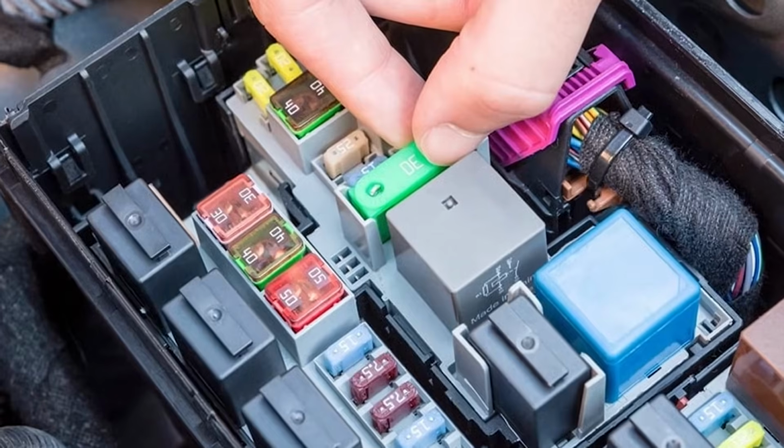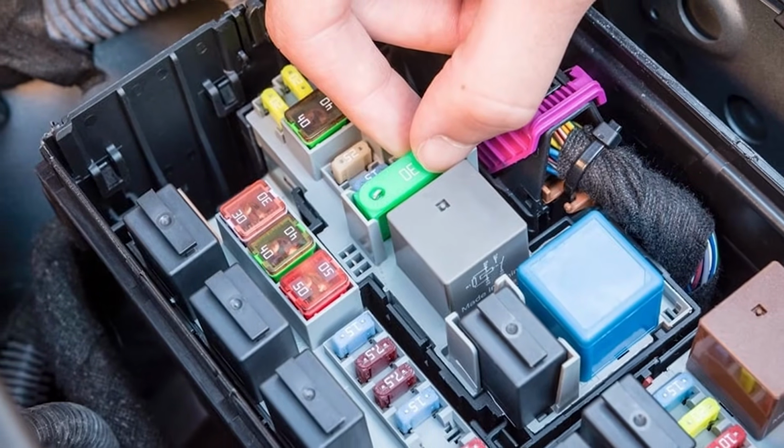After that, if you know it's something related to the electric cooling fan or the relay, and you're just getting fault code P0480, then the next steps are to start with the very basics. So first off, pull and inspect the fuse that controls the electric cooling fan on the vehicle. Locate your fuse box and check that fuse, make sure it's not damaged. After that, check the wiring and all of the connections leading to the electric cooling fan. Any damaged wiring, loose connections, disconnected sensors, etc. could all cause this issue, so just make sure there isn't any visible damage or loose connections.